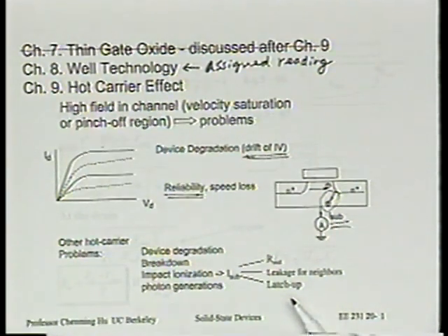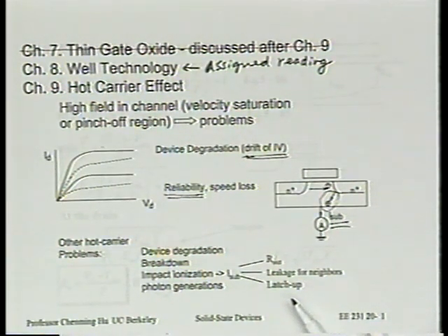But we talked about latch up, I think, last hour, the hour before. And we did say that today, latch up is not a very serious problem because design rules are very carefully fashioned such that we really minimize the shunt resistance between the base and the emitter, the parasitic base and emitter, and try to take the bipolar transistor out of commission, so to speak. And as a result, latch-up is not something we worry about every day. But if latch-up is a concern, it turns out I-sub is one way that can trigger latch-up.